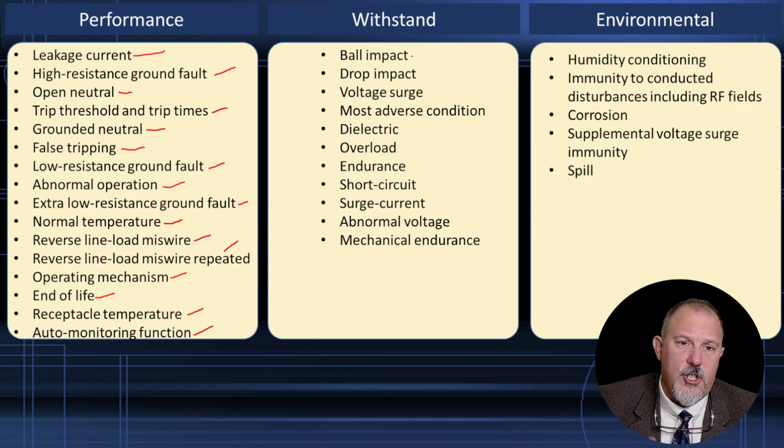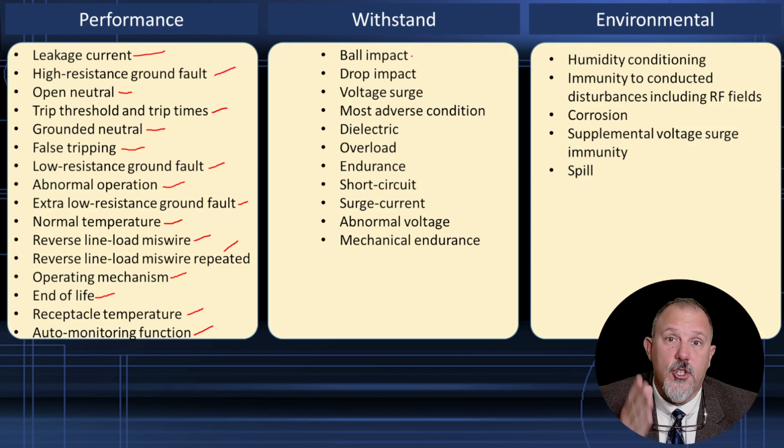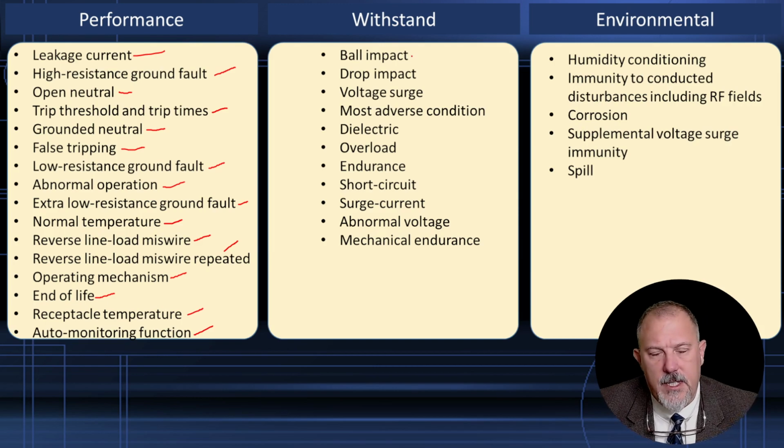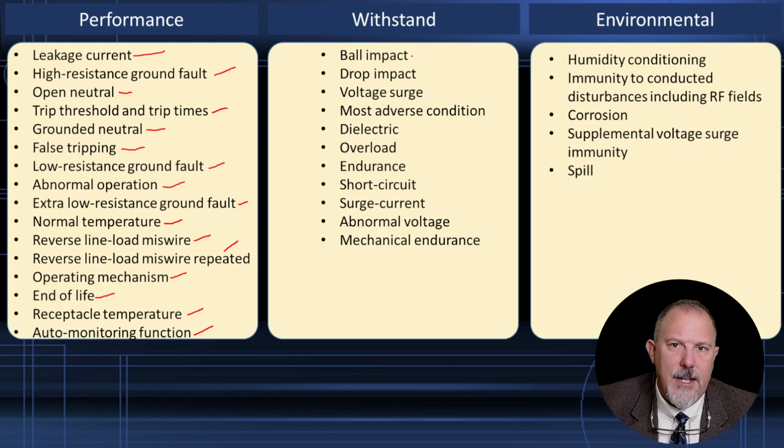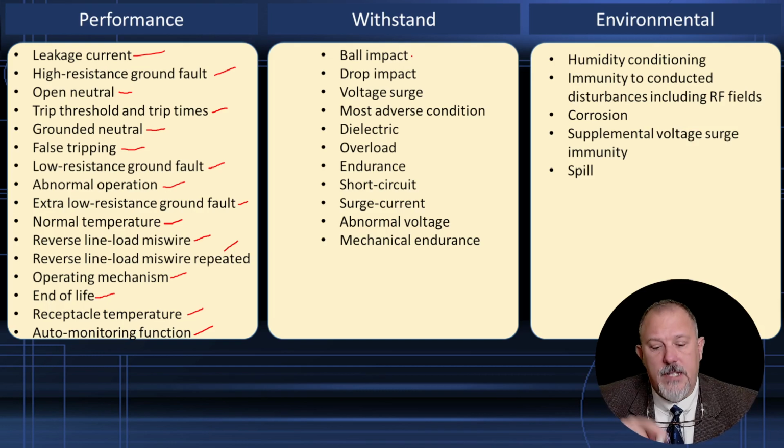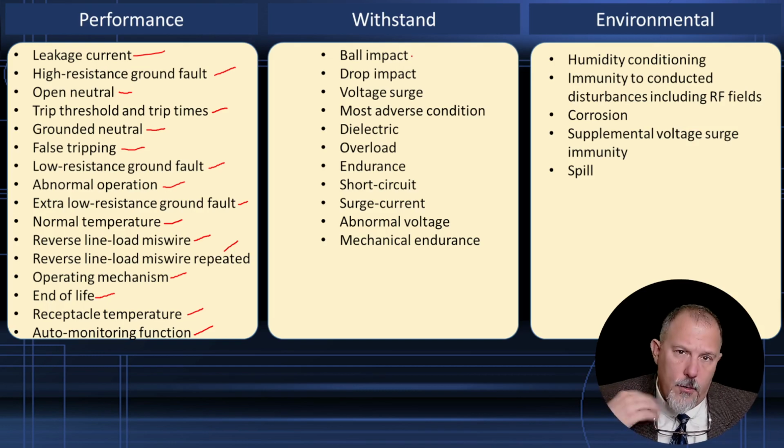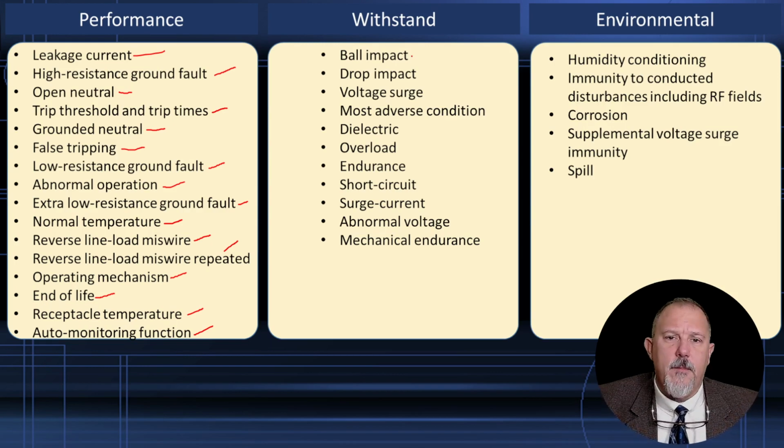I've got to think about voltage surges. And then most adverse conditions, dielectric capabilities, overload, endurance, short circuit tests, my surge currents, any abnormal overvoltages or undervoltages. And again, the mechanical endurance, push and test reset button. How many times can I interrupt the flow of normal currents when I'm pressing this test button? I've got to be able to do that over and over and over and over. And then you have your environmental, your humidity, your RF, your corrosion, your spill.